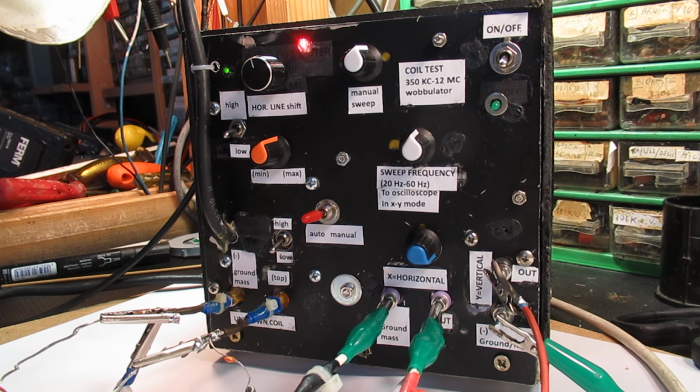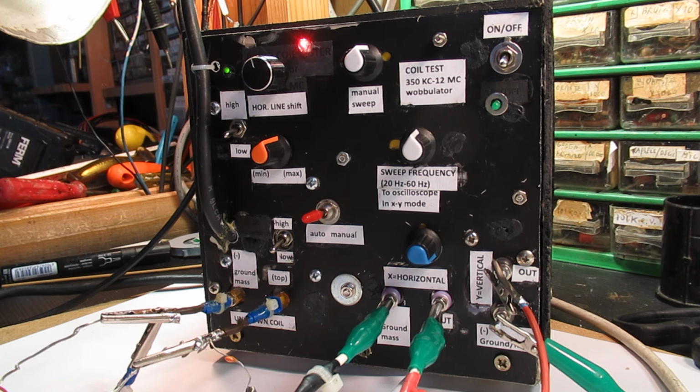In this video I want to show how you can use my Wobbulator circuit. A Wobbulator means that we test a radio coil under certain circumstances. We test it on its resonance frequency, we test it on its Q, its quality, etc. So I want to refer to an earlier video that I made, and will give the link in the description